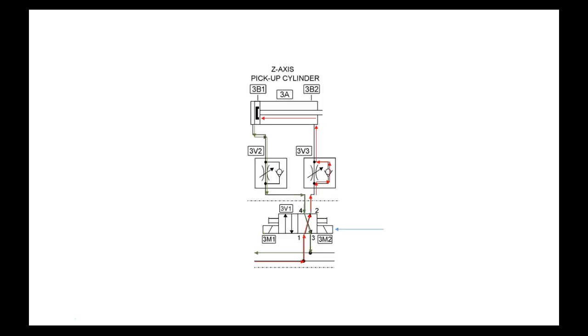So right now, the flow control, this is a check valve. And the check valve only lets something flow in one direction, and it's opposite of the arrow. What you're visualizing is when the pressure comes up, it's going to unseat that little ball and let it come through. When the pressure comes through on the other side, it's going to seat the ball, right? You understand? This is the flow control valve right here.